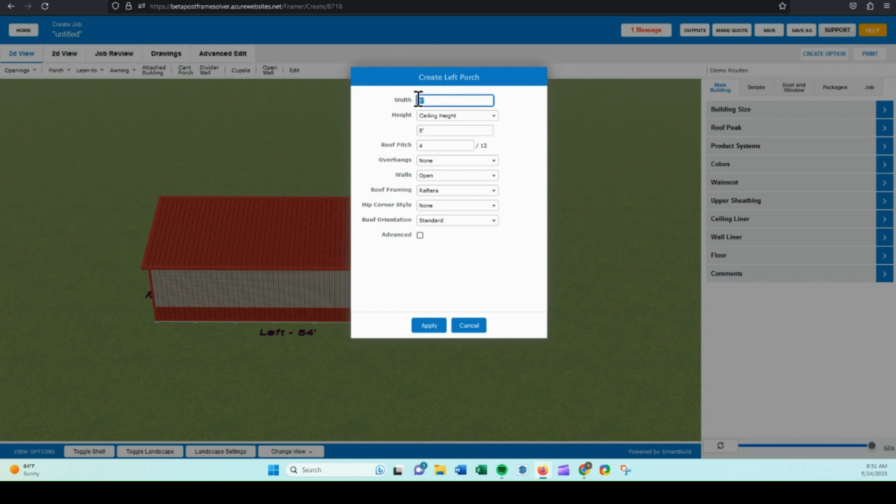So if I set this to 10 feet, and in this case, I'm not sure exactly what this height would need to be on the top side, so I can have it calculate that for me, and I could set it at offset down. An offset down of 0 will match up your main roof line. So I had a 6/12 pitch on my main roof, and for this, I want to break that pitch a bit and flatten it out. So we'll go with a 3 on the porch. To follow the overhang size, I'll stick with a 1 foot. That's what I had on the main structure.